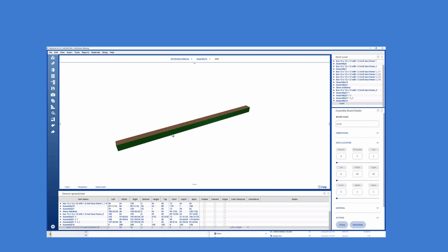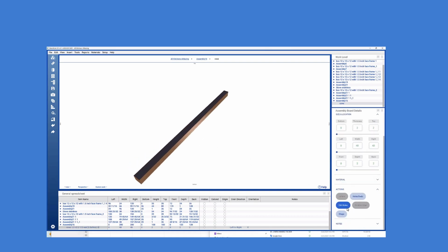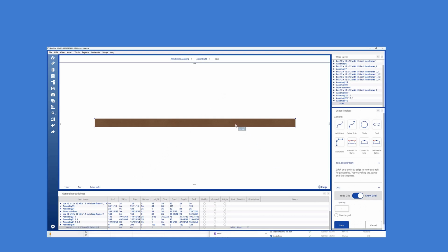To shape the boards for the miter cuts, select the top or blue surface of the board while at the board detail level. Shaping is allowed only on the surface of boards. Then click the Shape button at the lower right corner of the screen. A two-dimension image is displayed with dots on the 4 corners. Click the top right dot to select it.